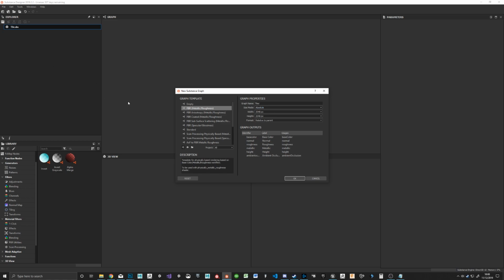I only want to see one graph per file. So I'll receive 5 SBS files from you guys, and you're only going to have one graph per file. In here, you can tailor at 4K textures, but for the most part, I only want to see like 1K or 2K textures put into Unreal. We can tailor these after the fact. It's great to work high and then we can export low. So for the purpose of this demo, I'm only going to do 2K textures.